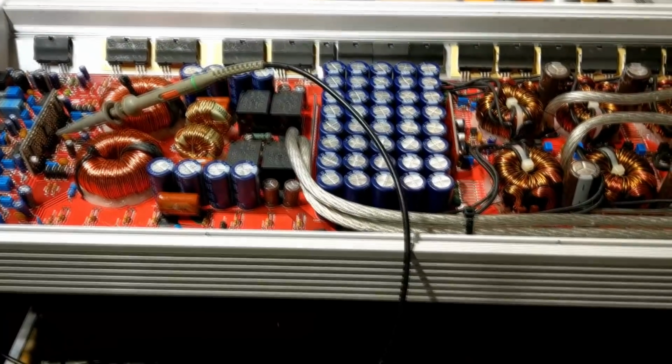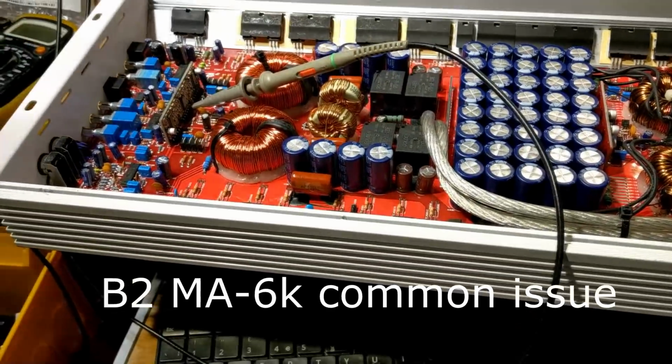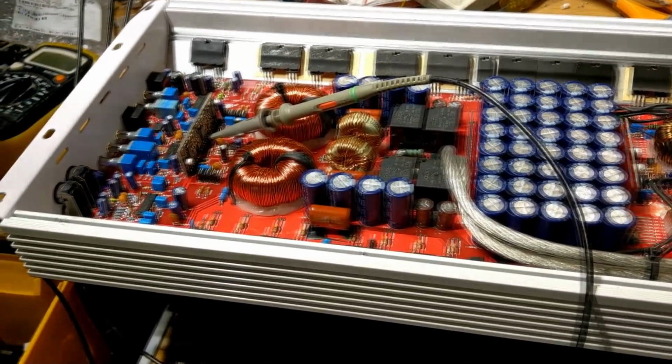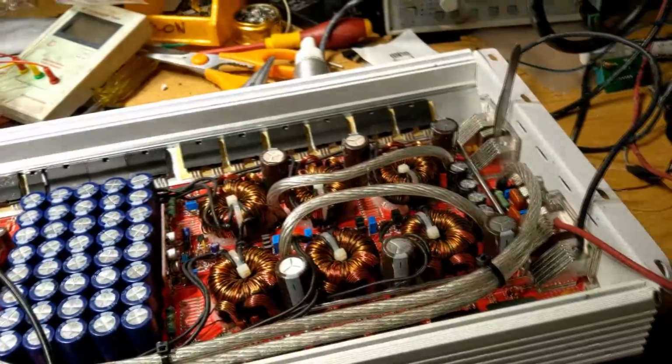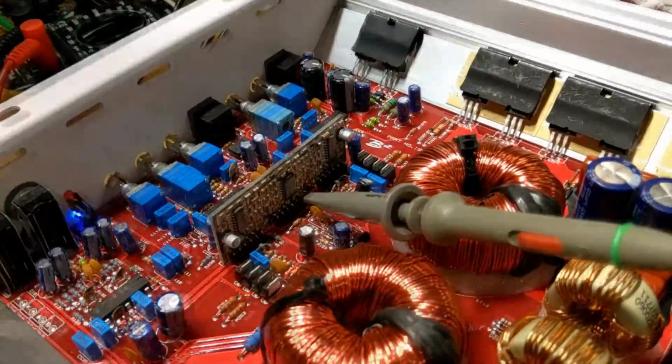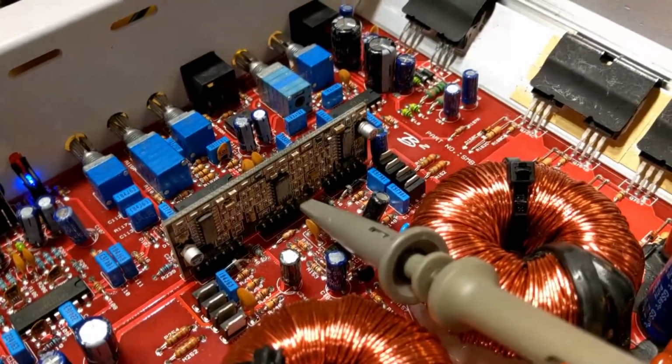Okay, gentlemen, MA6K, common fault. The amplifier keeps going into protection randomly, at random times after being powered up. It can be running idle, it can be running a load. It just keeps going into protection, and we don't know why. Common issue. After replacing a bunch of things on the output driver card, can't seem to find the fault.